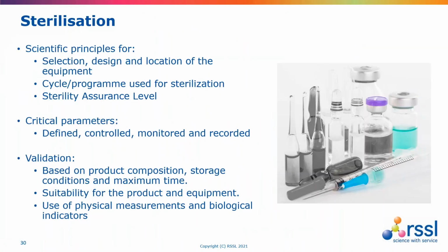And as part of the contamination control strategy, there is a stronger emphasis upon constructing a rationale for sterilisation: the selection and design of equipment, understanding the cycle, understanding the sterility assurance level, the approach to validation, the matrix approach adopted for determining those autoclave loads that are going to be qualified, and using appropriate biological indicators.